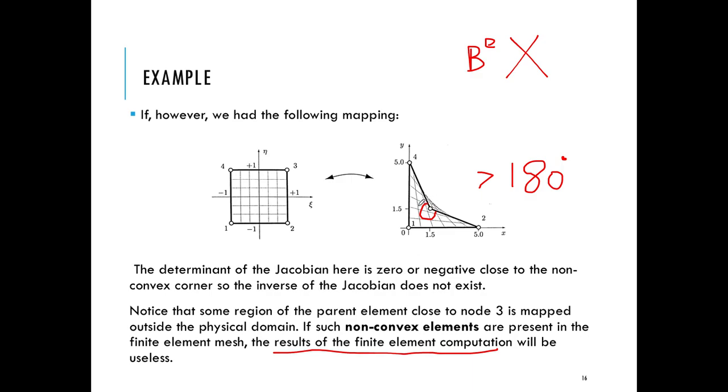Now wherever you have a corner which has an angle greater than 180 degrees, basically what ends up happening is that this element is no longer convex. Convex means that if you draw out a line through it, it would only cut it twice. Whereas look here, this is a non-convex, or concave, element where you have the line cutting it 1, 2, 3, 4. It's cutting it more than 2 times. So non-convex elements are not allowed in finite element analysis.